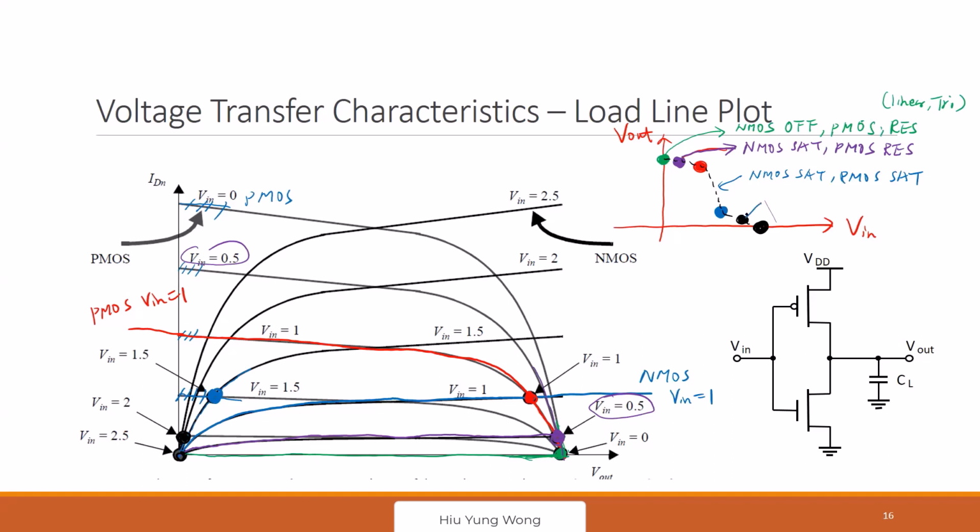And then you're going to swap. Can you guess what will happen to the NMOS when you go to high? Because now that you all fall to this region, right? So NMOS is what? Triode. Triode, yes. Right, and then PMOS continues to be at saturation. But eventually what happened? NMOS is still in the triode region, resistive region, and PMOS becomes, at this point, just a straight horizontal line, right? Off.